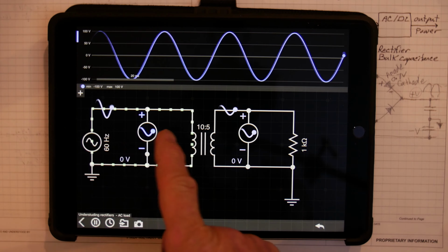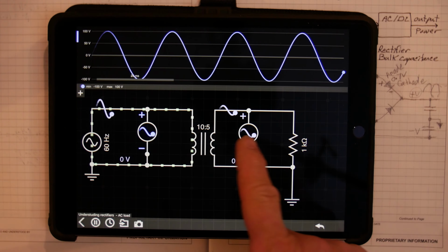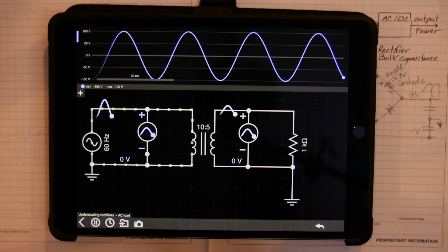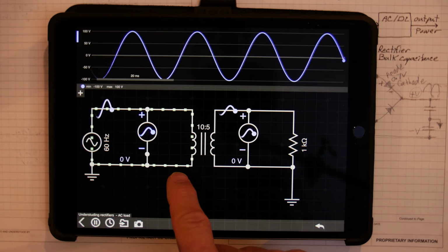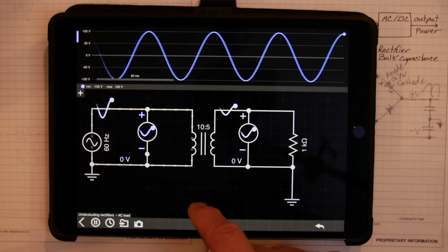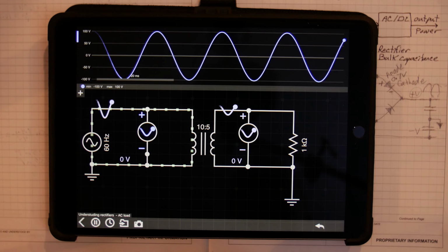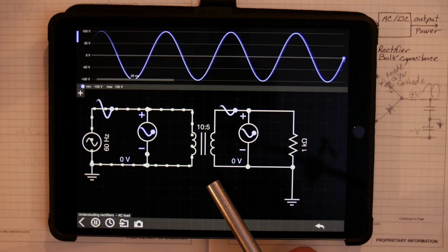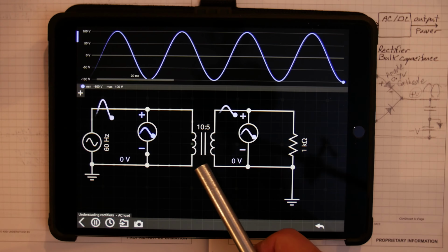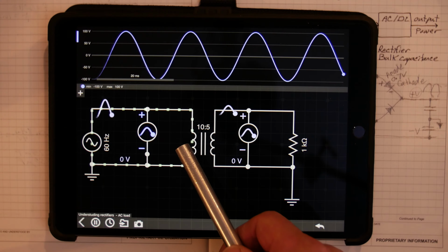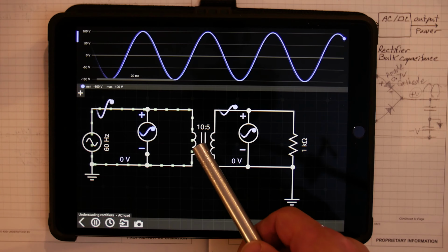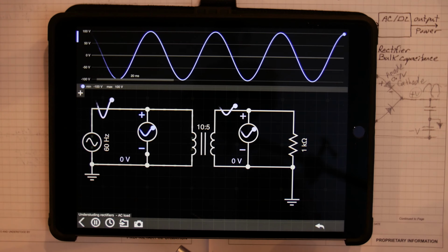By the way, this is a primary side, primary power, and this is secondary power. Secondary power is derived off of an isolation transformer, and that's shown by a coil here and a coil here with 2 bars in between, meaning that it has an iron core or some kind of core, ferrite core or iron core. So it's not an air inductor, and it's a transformer. So we're transforming and stepping the voltage down 10 to 5, which is 5 goes in 10 twice, so it's a 2 to 1 step down transformer.